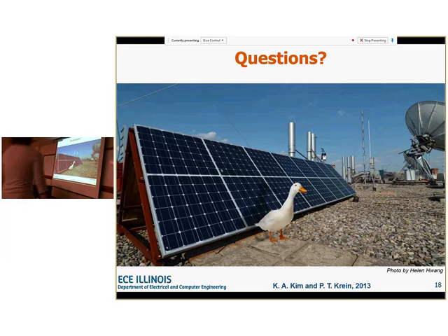So you found that 2x was sort of a safe place. How does that correspond to the duck? As in, if you have 12 of these, say in a string, and they can all produce full maximum power, right? So it can be a worst case of 11x power through one of these cells. Have you done any correlation between the shading pattern and how much shading that constitutes?